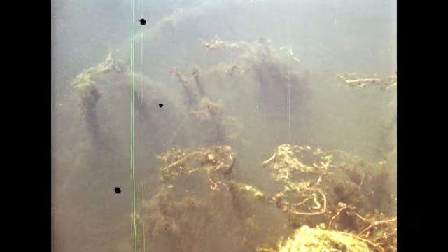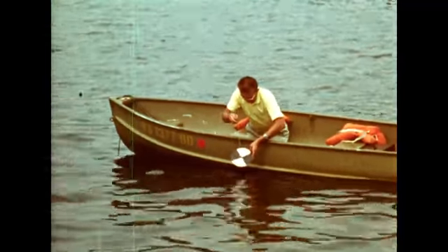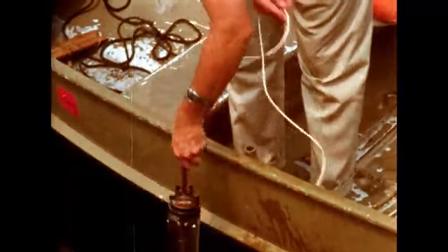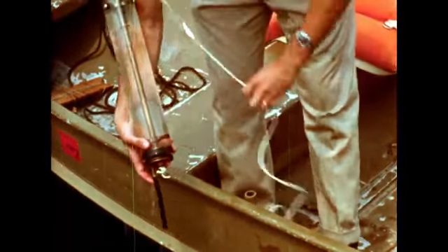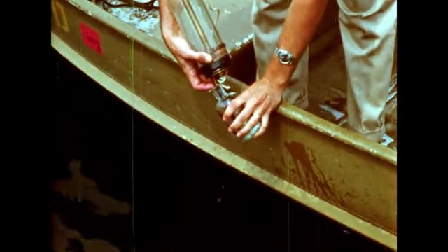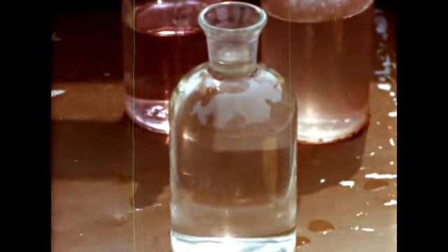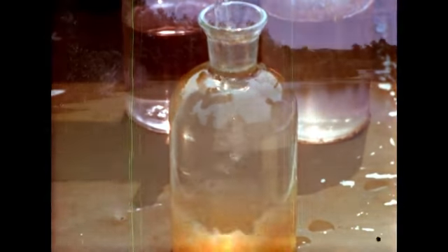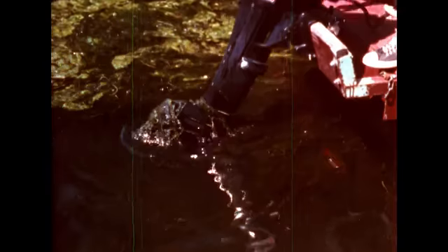Slow eutrophication can be beneficial in increasing the productivity of a lake. But in many cases, eutrophication is accelerating at an alarming rate. This can be detected by measuring transparency and dissolved oxygen content. As eutrophication progresses, transparency lessens and dissolved oxygen decreases in the bottom waters. Blooms of algae cause taste, odor, water filtration, and other problems.